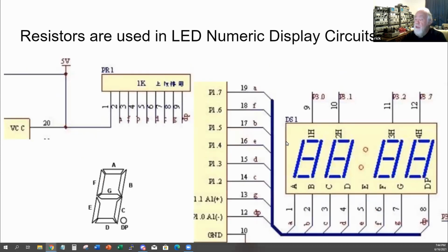Here's a small section of the circuit showing just the microcontroller and what we call a bus that connects the microcontroller output port to all of the segments of the LED display. And as you can see, here we have an A connected to A here. We have a B connected to B here. And so when we look at these identifying labels, these are the logical pin numbers of the chip that tell which output bits the program's referring to.